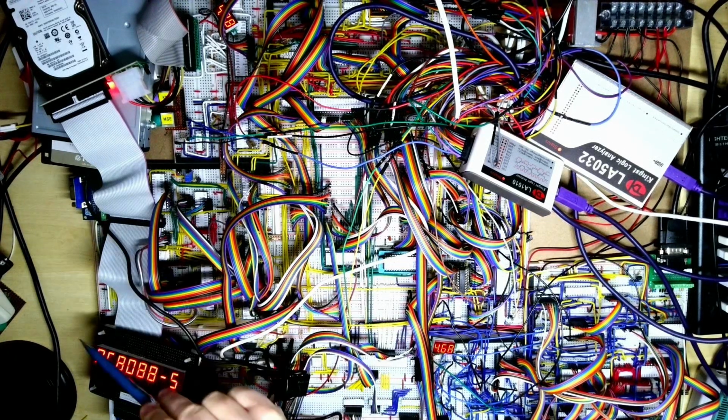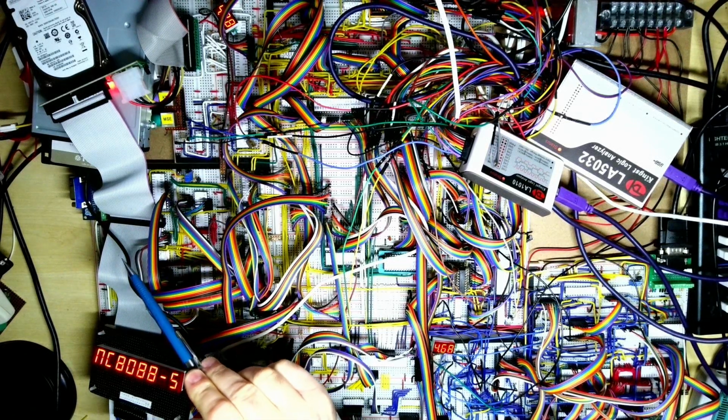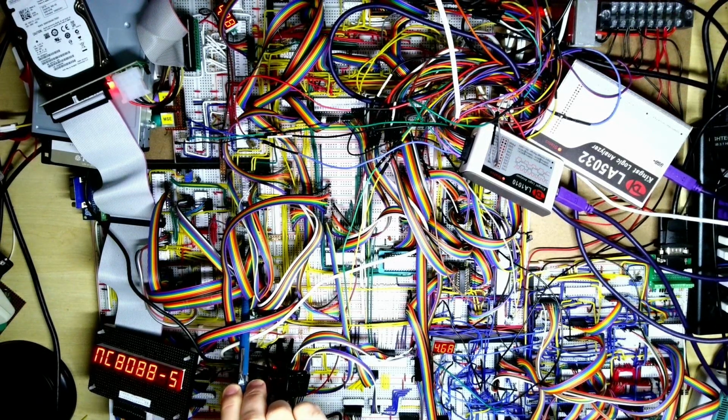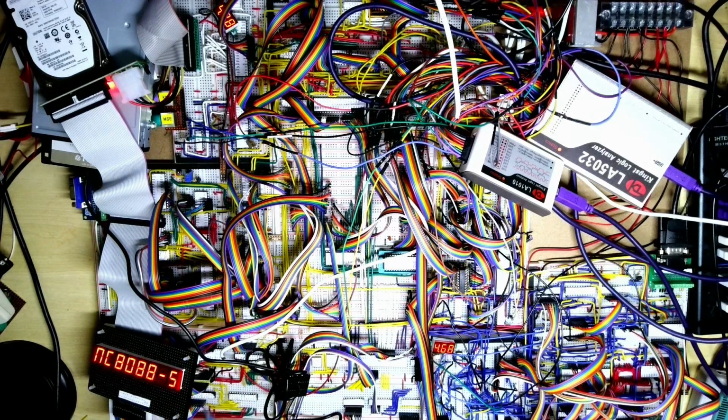Now over on the left hand side here, the first video card we built was a monochrome display adapter compatible one. This is a bit simpler than the later one we did in that there is a large RAM chip here, and this is a dual port RAM chip. So this has data and address lines on both sides of the chip, so we can hook it into the rest of the computer and also into the cathode ray tube controller that runs the video card here, and we'll never actually fight over access to the RAM.